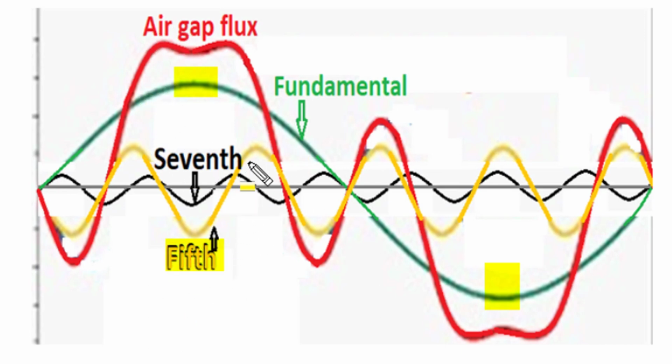And in the 5th harmonic flux distribution, every time the flux peak changes its direction, the polarity of the pole will also change. And in the 5th harmonic, we find that if the fundamental frequency component of the space wave produces two poles, the 5th harmonic will produce 10 poles, and similarly the 7th space harmonic of the MMF wave will produce 7 times the number of poles as compared to the fundamental flux wave, as illustrated here.